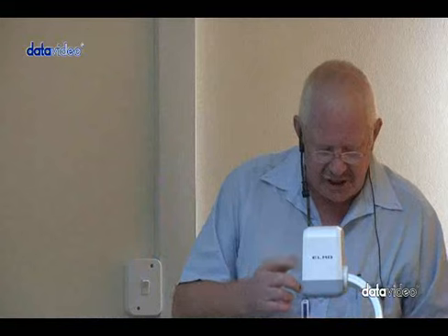Exactly what I told you, right? So I didn't lie. This increase in the voltage across RC means that the voltage at the collector decreases from the Q point. They didn't say why, but I told you it's because of Kirchhoff's voltage law, right? So, any change in input signal voltage results in an opposite change in collector signal voltage, which is phase inversion. Okay, make sure that you understand that.